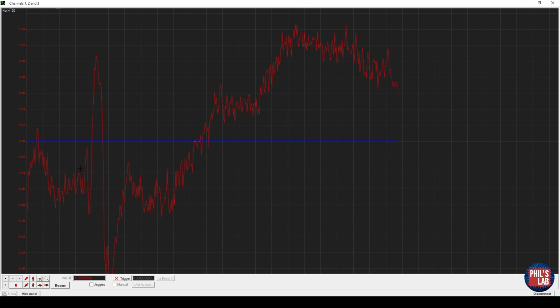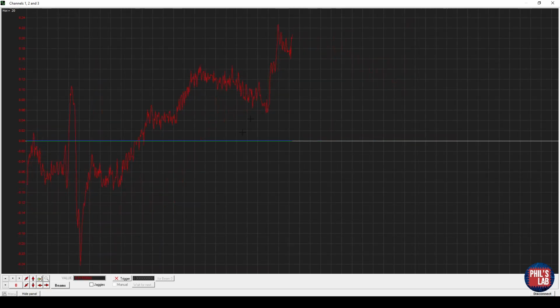So let's see what happens if I lift it above the table. Let's see if I can try and lift it about 10 centimeters above and change my scale, and you can see it's moved up to about 20 centimeters. I can move the board down again, and it takes some time for it to settle, but it's moved back down to about 10 centimeters. So this change needs to be about 10 centimeters, which is how much I moved. I can also move it down. So below the table, you can see we have these initial transients. I'm just doing it by eye, trying to move it down 10 centimeters, but we definitely see a movement, but you might get an error of plus minus 5 or 10 centimeters.